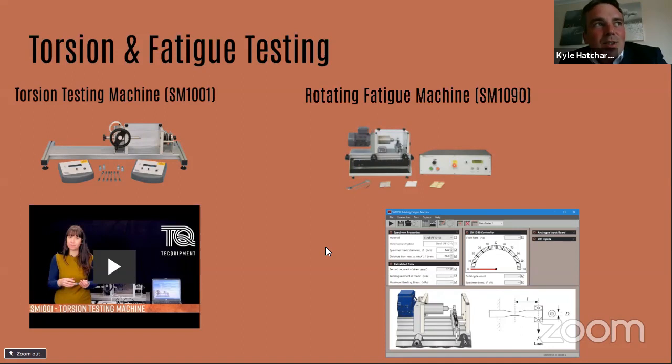And again, we talked about cycle rates within a fuselage in an aircraft. It's about continually applying a cycle rate to a specimen. So you can see in that picture there very faintly that you've got a specimen applied to the front of a motor, and you cycle that motor over a period and apply a load with a series of weights on the bottom arm there. That then allows the material to be offset ever so slightly.